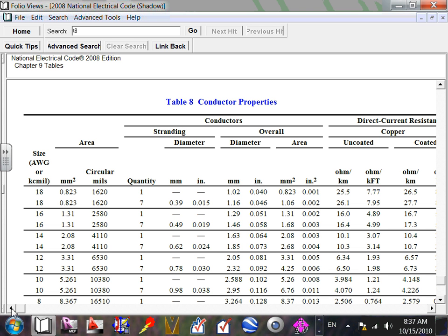When we do a voltage drop calculation, guys, there's a few things we need to take into consideration. Voltage drop is a recommendation in the NEC code book, not required. It's a recommendation, but in the engineering community, it is required. You have to check for your voltage drop, otherwise your equipment might malfunction.